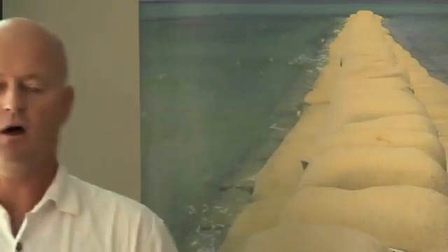And with rock structures, the generally accepted coastal engineering standard is you're allowed to have up to 5% of rocks move from where they started, and that's still considered no damage. Because there's a lot of flexibility in rock structures, 5% of the rocks can move from where they started, and it's still considered a no damage criteria in inverted commas. For geotextile containers, there's still flexibility compared with a rigid, solid, say a brick wall. There's flexibility, but probably not as much as a rock rubble structure.